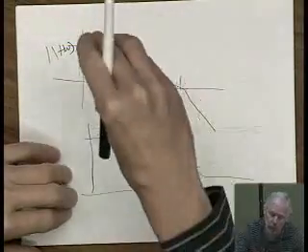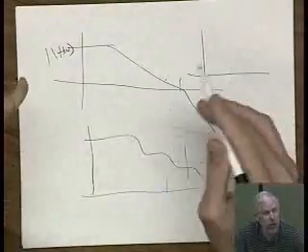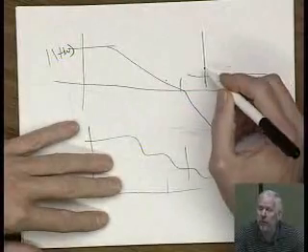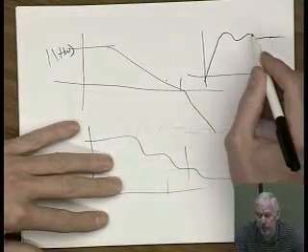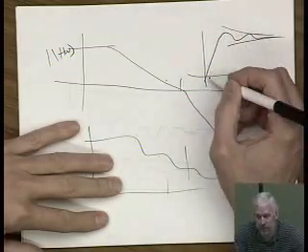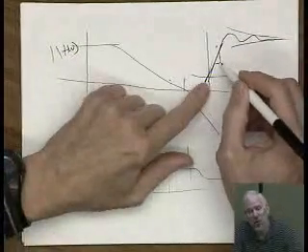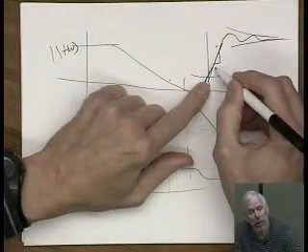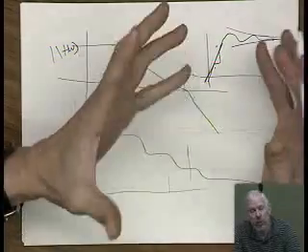Okay, use magnitude and phase, and for the final FOM, as you're figuring it out, look at the transient response. I mean, look at how this thing looks. See if it's ringing. There's slew rate, there's part of it. There's the small signal settling part of it. Look and see what's really going on.